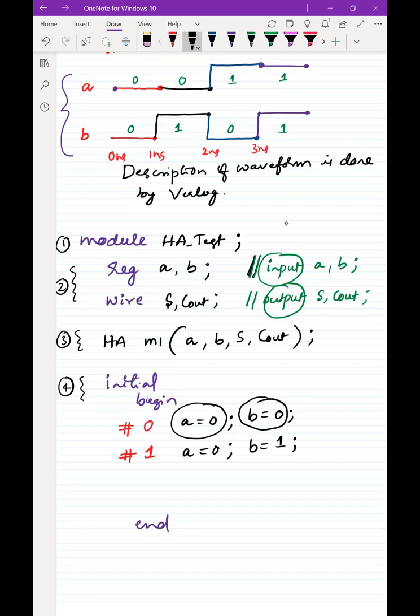Now the third one: if you use another 1 nanosecond, if you want to get the 2 nanoseconds here, we have to add another 1 nanosecond, not 2 nanoseconds directly. Okay, therefore it becomes 2 nanoseconds now. So the delay is added from previous value to the next value. So if you want to get the succeeding one, we have to add this delay to this one. So therefore, here the current value of this one is 2 nanoseconds. It becomes like that. Please remember.